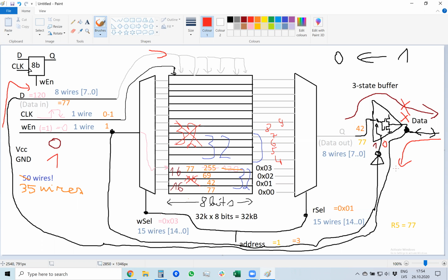And if it's output, either output low or high. It is done exactly with this 3-state buffer. If it's output, then either it will be high or low. And if it's input, then at the same time, high and low are disconnected, and it's input. It's not giving anything out and it cannot burn anything. So this is how memory is organized.